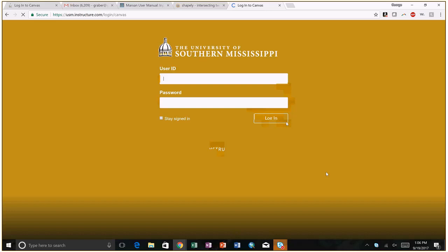The two modulated signals are the coarse acquisition code and the P code. So the CA code and the P code. You can see the difference in the frequency. This one's a higher frequency than this. The P code, the precision code, has a higher frequency.